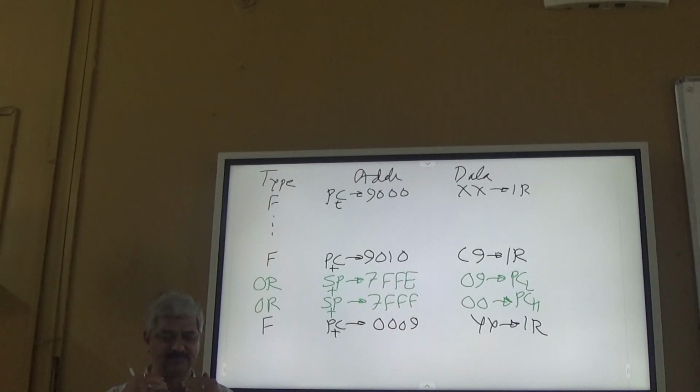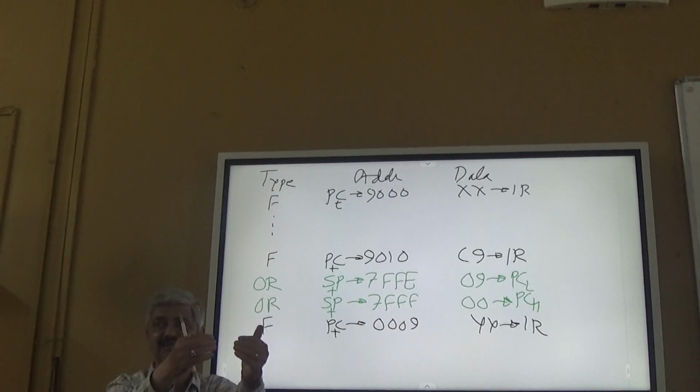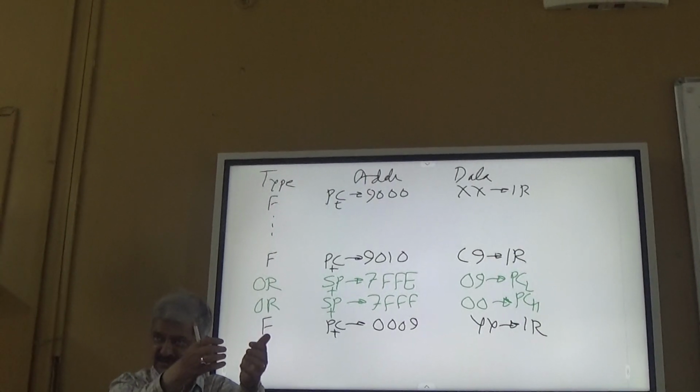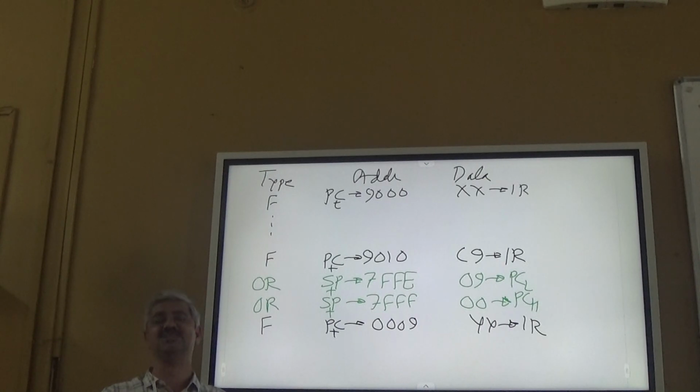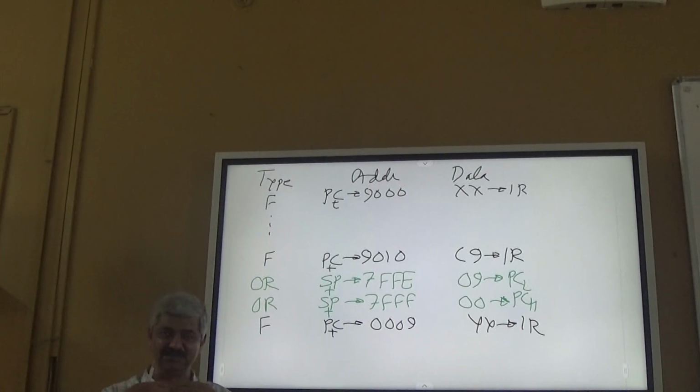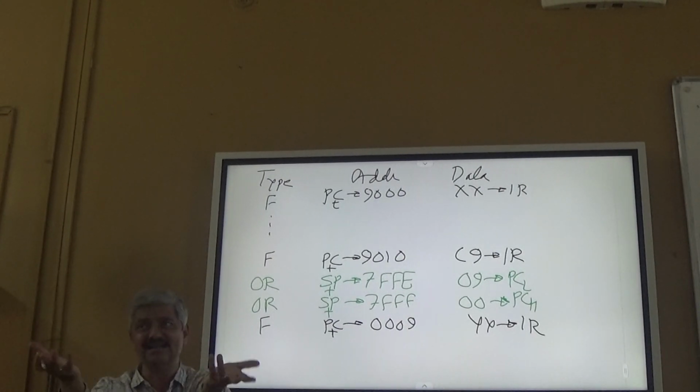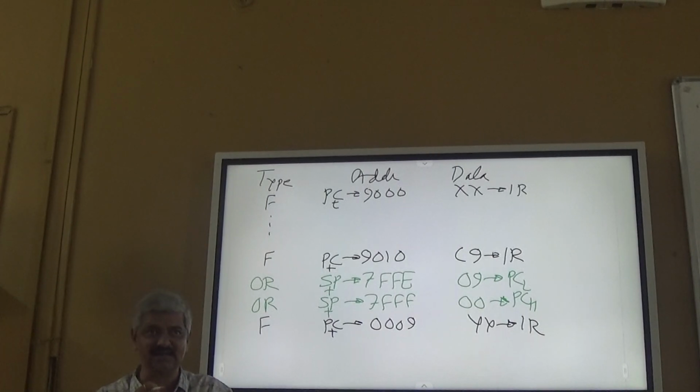So I call the subroutine with operands in HL and the subroutine returns the multiplication in HL. Naturally I expect that the other registers should not be changed. But then I can't write the subroutine, since I can't write it by keeping other registers intact.